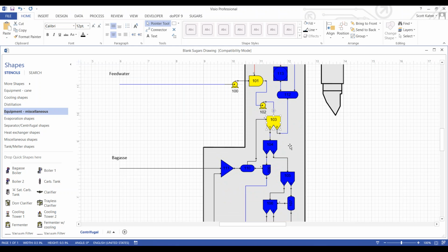Now, if all we were doing was burning a constant fuel, like natural gas or even possibly a coal that's basically constant all the time, the fuel doesn't change, that separator would be the end of it and the fuel could leave as ash. However, bagasse is variable. It has variable moisture content, variable sucrose content, and therefore variable combustion energy. So this boiler grouping actually has ways to account for all of that.